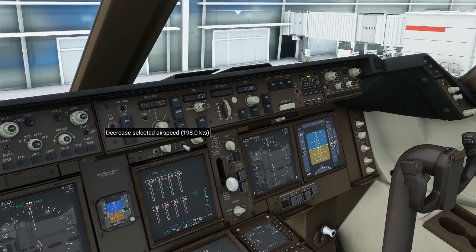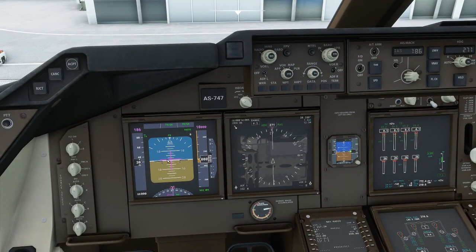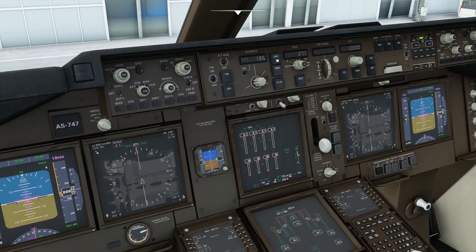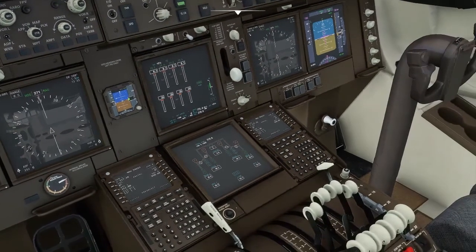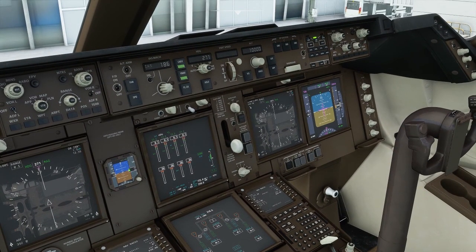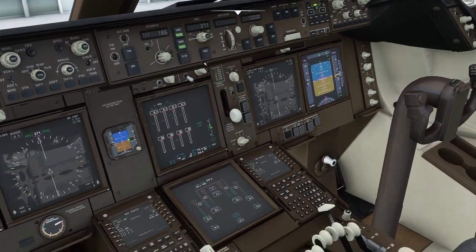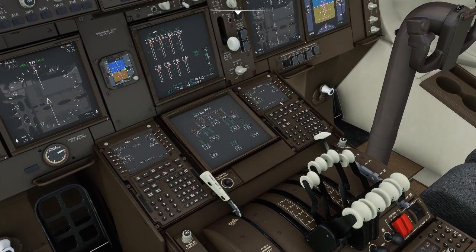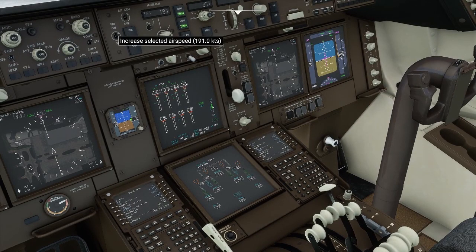So you would normally set your V2 speed that the computer's worked out for takeoff. You would always have your flight directors on now, so that's them on, and these pink lines come up and it says TOGA TOGA. That's for takeoff. And then you would probably have LNAV and VNAV armed, because the other guy will have programmed the FMC. There is a kind of data entry procedure for putting all your performance details into the computer, so you would do that together to make sure you don't make any mistakes. And then you would go to your takeoff page, and you would fill this all in together, and then it says V2 is 229, so you would set 229 in this window.